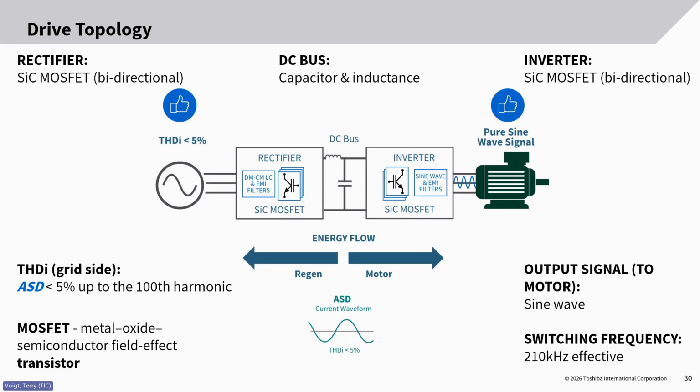That's extremely low harmonic regulation. I mentioned earlier that some engineering firms will say they want everything at 5% or below. This drive by itself will pass that. So that's on the front end. It has capacitors. There are some active front-end drives on the market that don't have capacitors; they're called matrix drives. They work very well, but the added capacitance adds some reliability to the system. So this has a capacitor and an inductor inside the middle section.